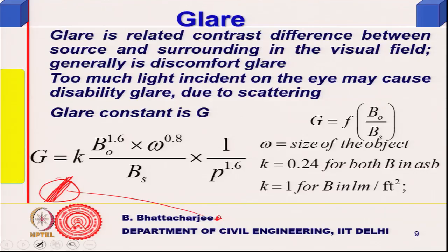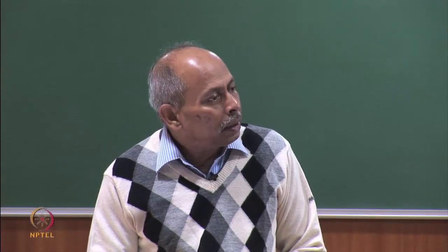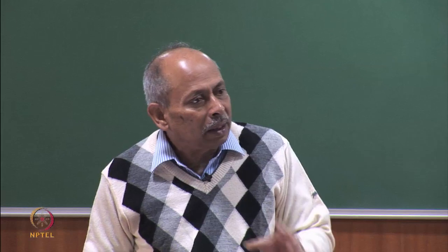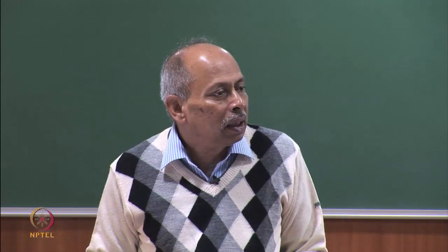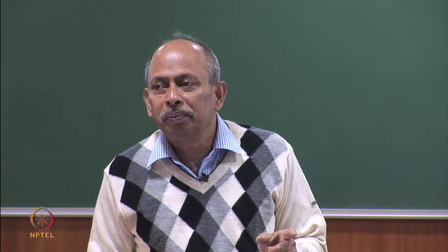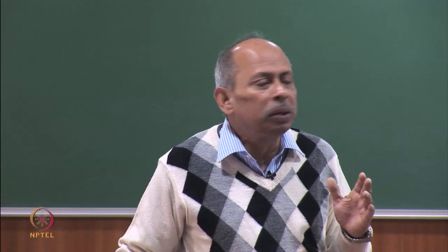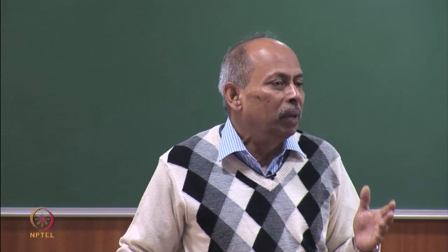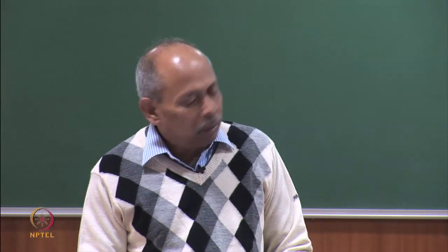If you know the total lumen output, that is flux, then flux divided by 4 pi r square will give you the illumination on the surface, lux, and 1 lux corresponds to 1 apostilb. Remember, 1 lux illumination corresponds to 1 apostilb, otherwise 1 by pi candela per meter square. So, you have to have a pi relation. So, if it is in apostilb, you can calculate out accordingly.